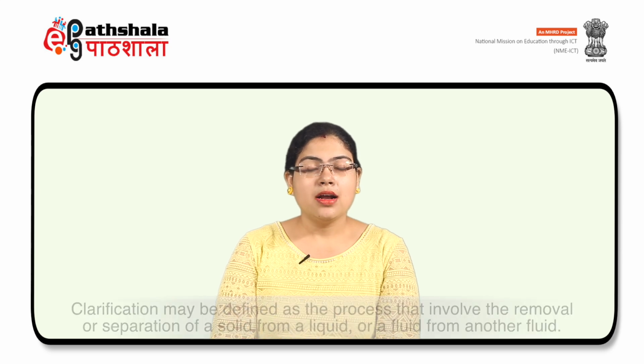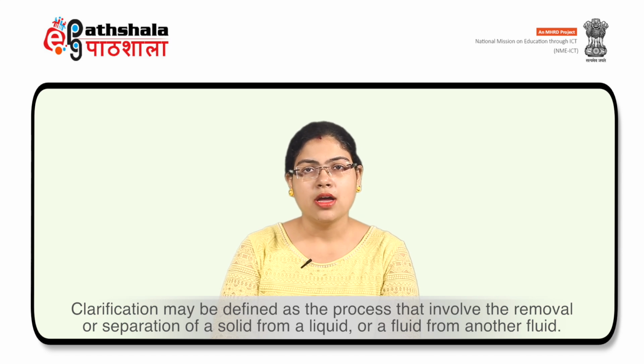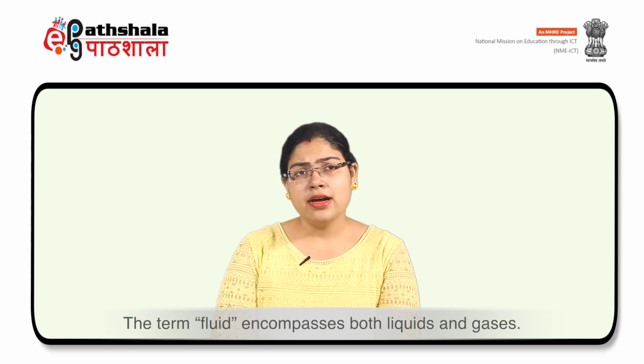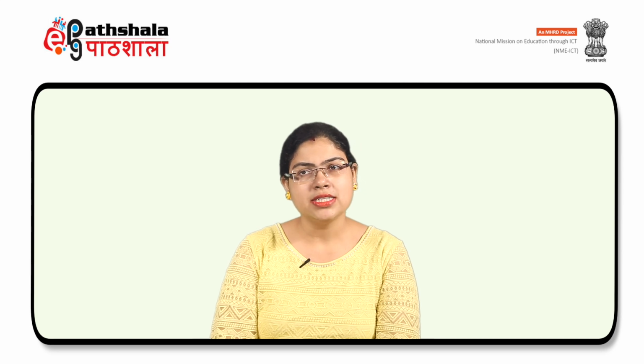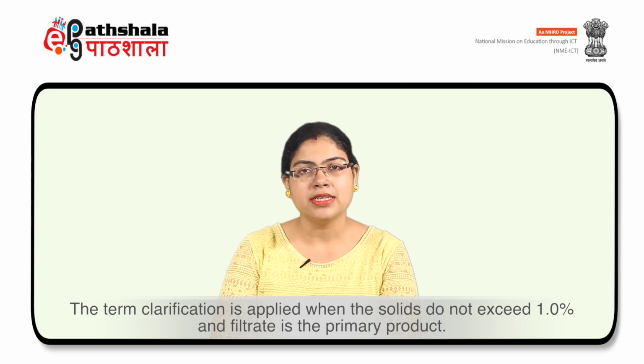Now, there is another term called clarification, which is part of filtration only. Clarification may be defined as the process that involves the removal or separation of a solid from a liquid or a fluid from another fluid. The fluid here includes both liquid and gases. Clarification can be achieved using either filtration or centrifugation techniques. The term clarification is applied when the solids do not exceed 1% and the filtrate is the primary product.